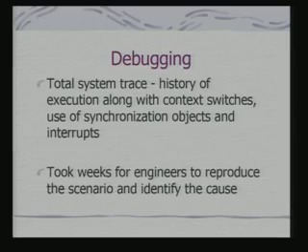So, what I was trying to illustrate with this example is how the different components in an embedded system are interdependent and they can interact, and if you do not take care of all their possible interactions, this can also be a source of bugs. So, debugging in such a case becomes extremely difficult. You have to do actual execution traces, follow the execution traces to reproduce the scenario and identify the cause, and these effects occurred when the rover was actually on Mars. And you have to have a complete simulation environment in the earth station to identify the fault and try to rectify it.